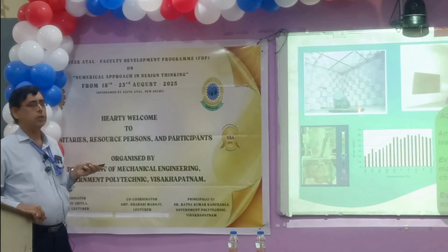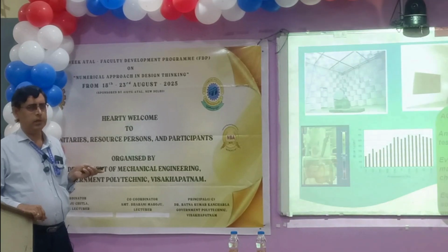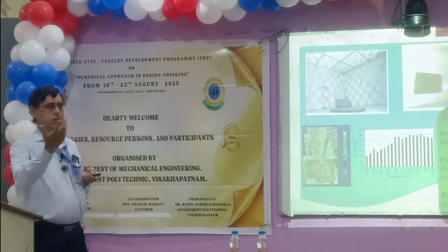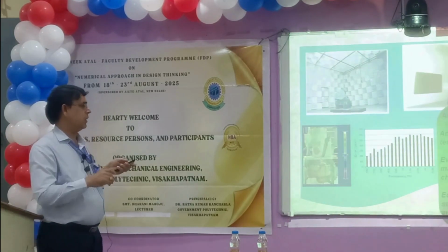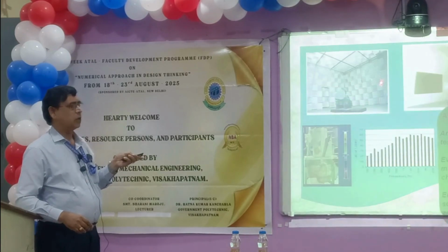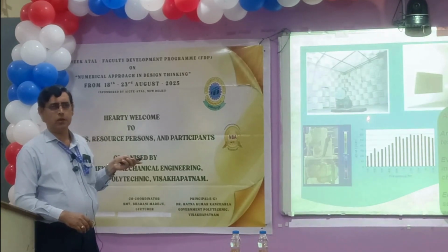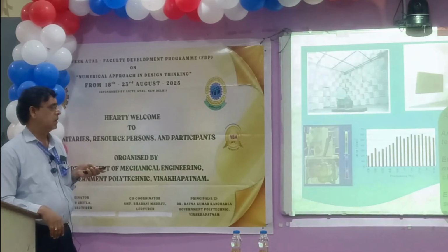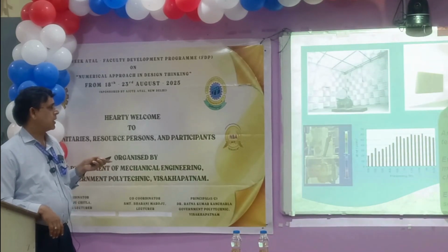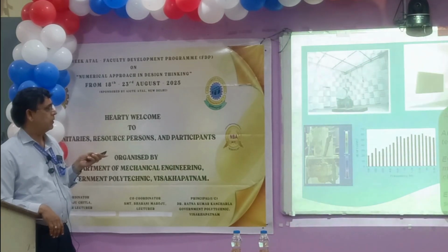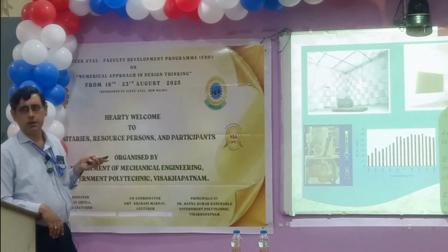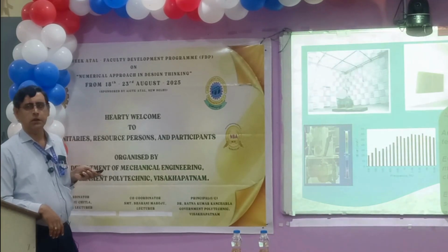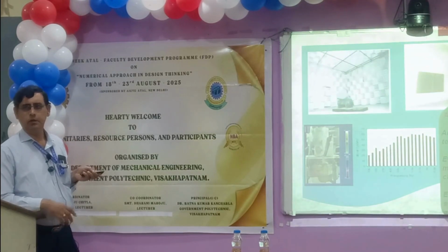Here in NSTL, we have this facility called anechoic chamber. Anechoic chamber means I talked about echo coming from these walls, right? The walls echo can be reduced by putting what is known as this kind of sound absorbing treatment. These are called sound absorbing wedges made of different materials, like you can use wool also in case possible. So this is complete, not only walls, even the top, you can see ceiling also is attached like that. This is called semi-anechoic chamber, whereas if you treat floor also with that, it's called fully anechoic chamber.